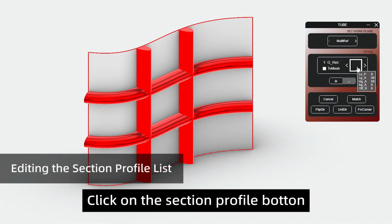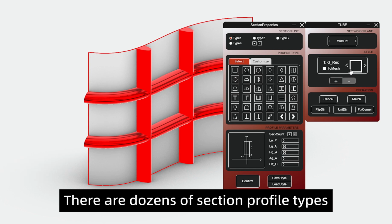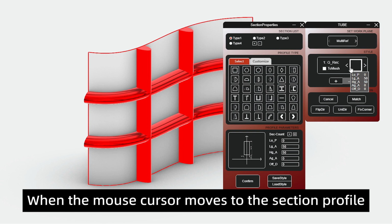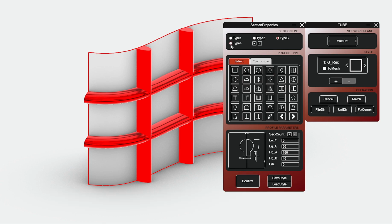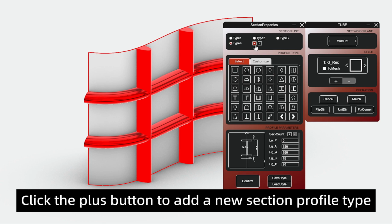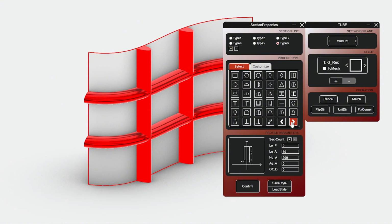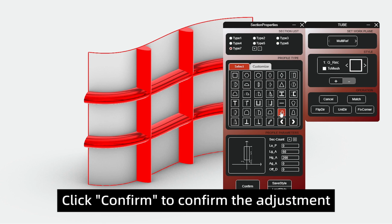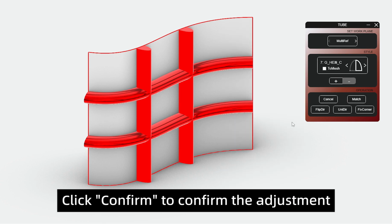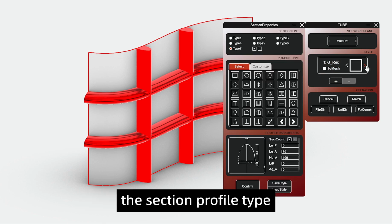Click on the Section Profile button to open the section profile list. There are dozens of section profile types. When the mouse cursor moves to the section profile, the current section parameters will pop up. Click the plus button to add a new section profile type. Click Confirm to confirm the adjustment. The section profile list synchronizes the section profile type.